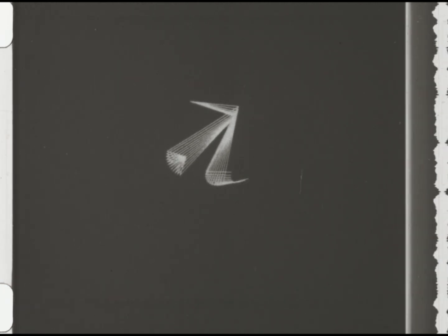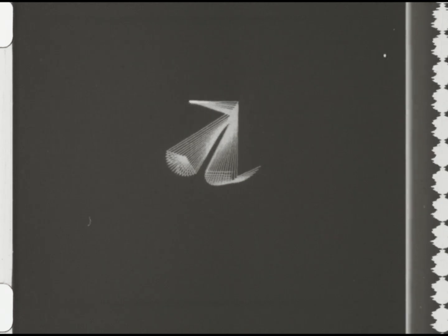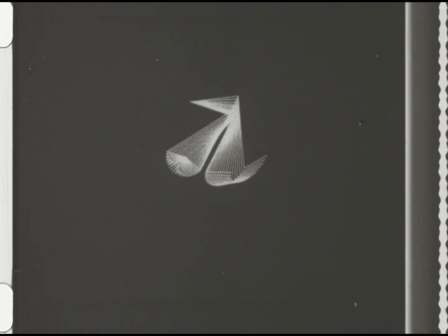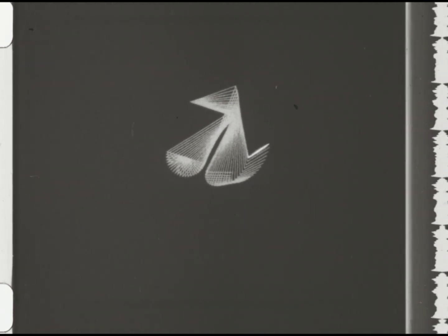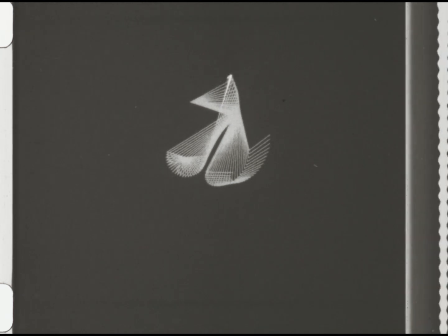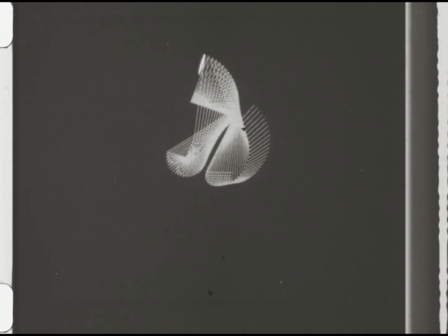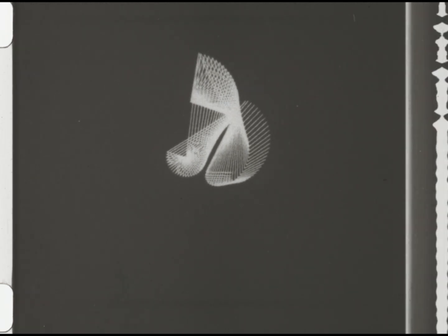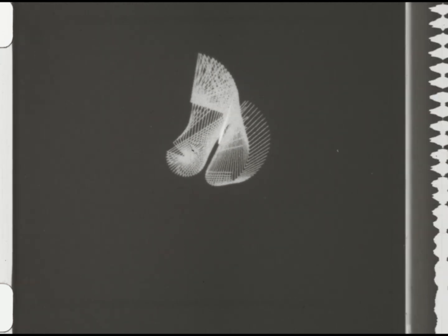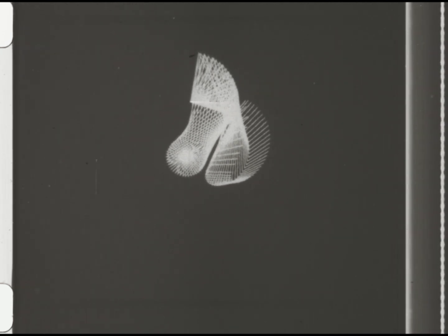This is a schematic representation of a 4-bar linkage mechanism. It is being animated on a computer display screen. What is unusual about this particular linkage is that it was especially designed by means of the computer to produce the particular motion which you see. Design of a mechanism to produce a preconceived motion is the process of kinematic synthesis and is the main purpose of the Kinsyn computer system.